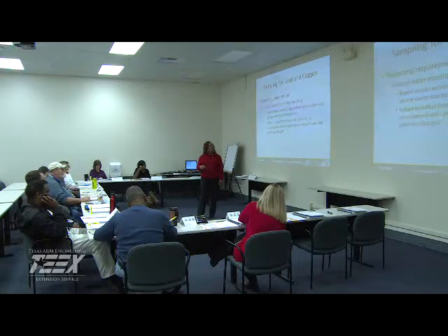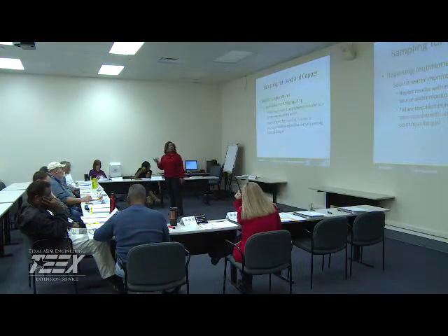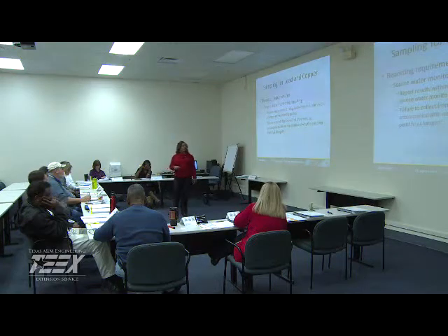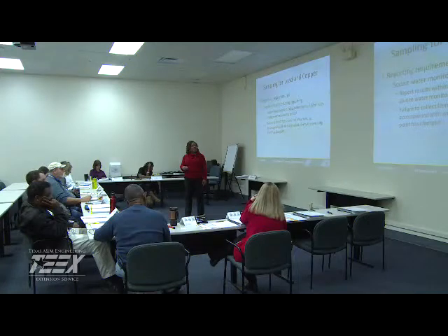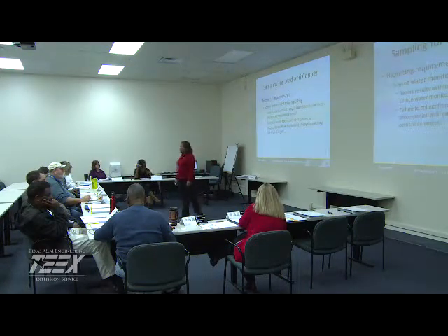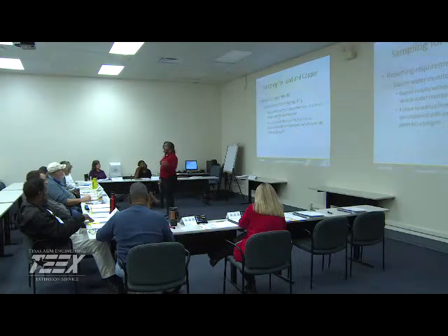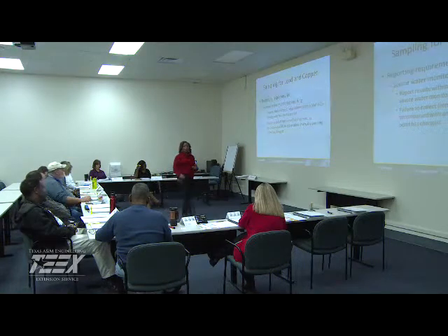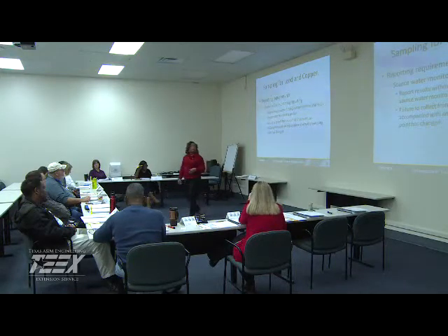Other reporting requirements, source water monitoring. Again, results are due within 10 days after the applicable monitoring period. Failure to collect from specified sites must be accompanied with an explanation of why the sampling point changed. So if I turn into the state a good sampling siting plan, and I choose to do another site or go another place, I better have an explanation. I shouldn't do it without, again, their approval.